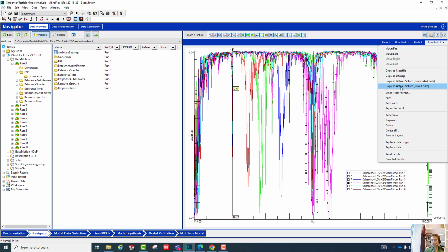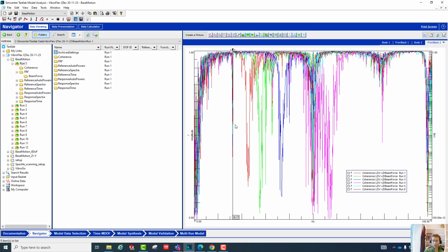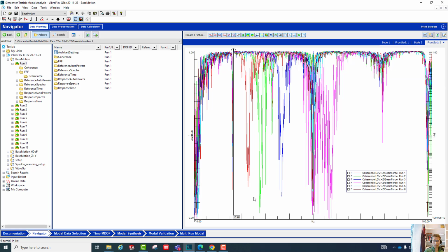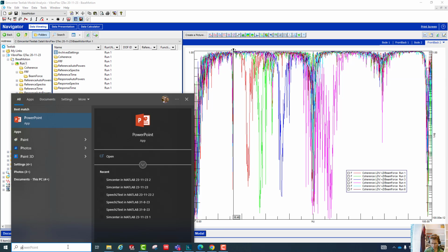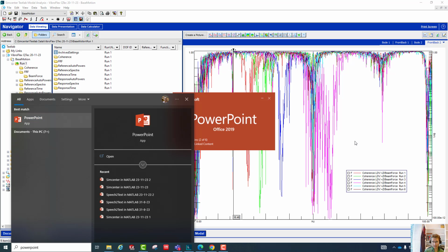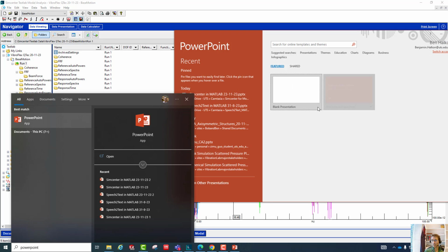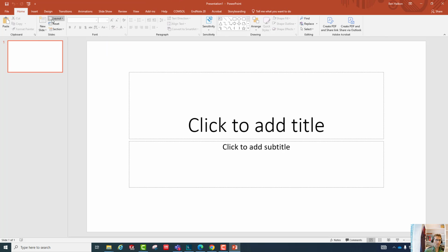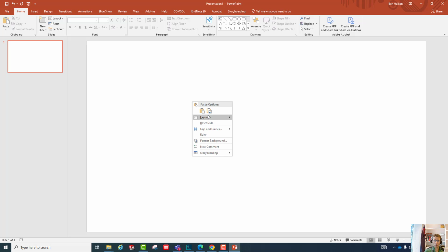A more interesting option is to use active pictures. So there's a free plugin available from Siemens Simcenter Testlab, which allows us to have this plot with these sorts of functionalities like an active cursor, the ability to move the legends around and paste those with the data embedded, which is preferable. It'll make for a bigger file than you would otherwise end up with. But it's better if you use an embedded data format for this than, for example, a linked data one, in case you move the project file after the fact and then the data is no longer available.